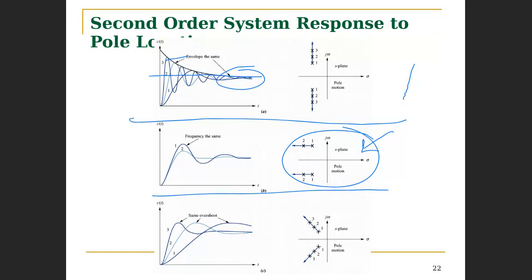I think it was the previous slide before this one, where you indicated that once you have two poles in the negative direction of the real part, it's more stable. Not recalling that, though. What I did say is that once you have the poles on the left of the imaginary axis, then the system is stable.